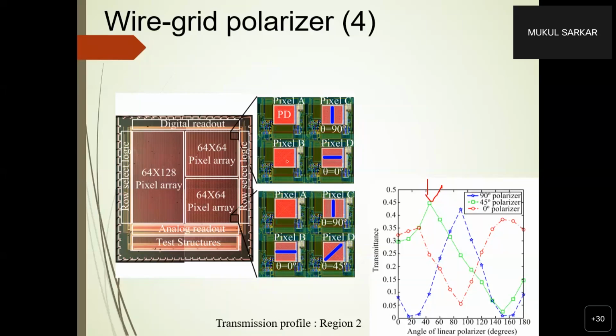Still, you have to see how to obtain a single shot. Most of the high dynamic range images that I've talked about are single shot. So in one shot, you get full HDR, right? Some sensors are multi-shot. You have to take two or three different shots and then combine the images to obtain a high dynamic range, right? Wherever you have multi-shot and combine the images to obtain HDR, those will be slightly power hungry. But if you do it in the sensor domain, in the analog domain, then the power consumption is substantially lower compared to when you do it in the digital domain, right?